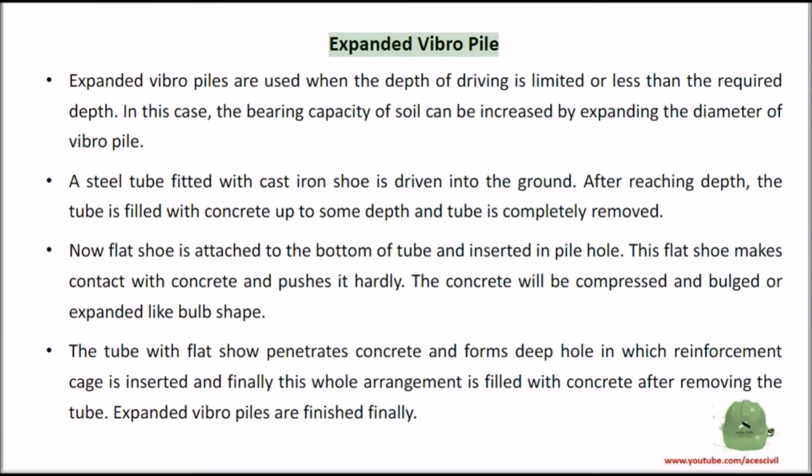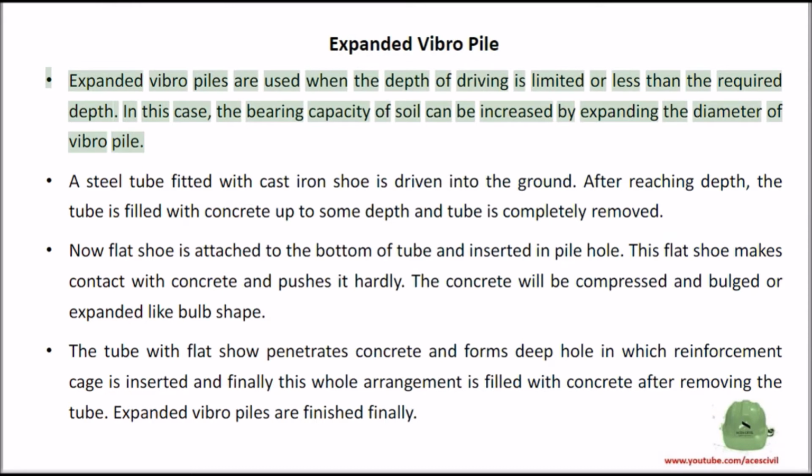Expanded Vibro pile. Expanded Vibro piles are used when the depth of driving is limited or less than the required depth. In this case, the bearing capacity of the soil can be increased by expanding the diameter of the Vibro pile.